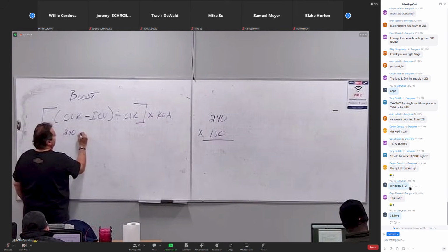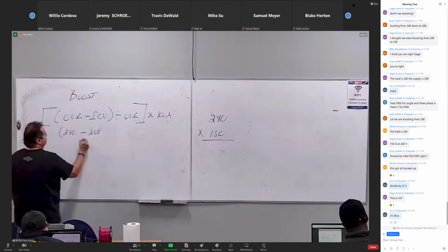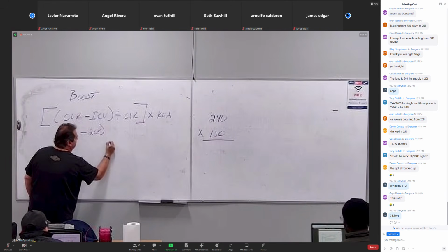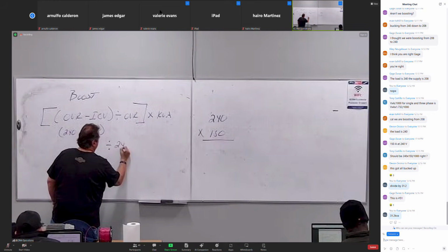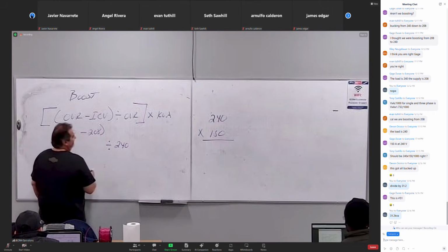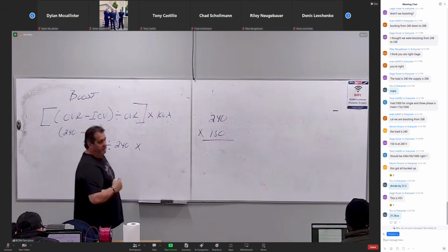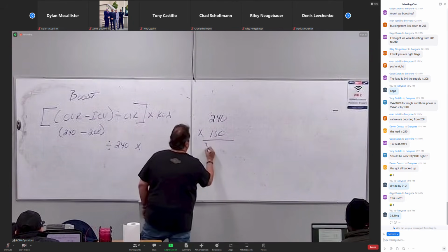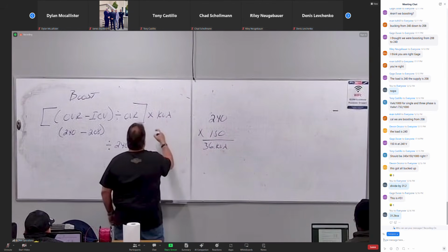My input voltage I have is 208, we're still gonna get basically the same ratio. We're then going to divide that number by 240, and then we're gonna multiply that times this number. 36,000, thank you. Or 36 KVA, right? Because they're keeping it at KVA.